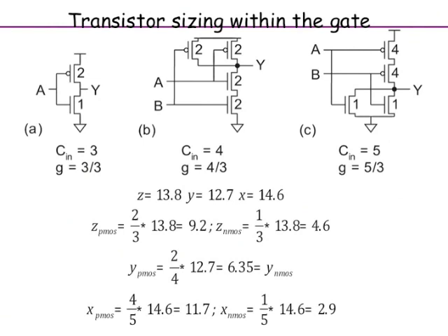Maybe not according to the linear delay model, but right. So the question is, do the commercially available logic synthesis tools do the optimization, and if so, how do they do it? You're right. Yes. Because you typically write digital circuits in Verilog, VHDL, or one of these high-level languages, the commercial tool will take that and figure out what logic gates will realize it, as well as find the sizes of the gates.